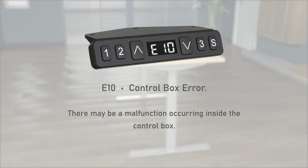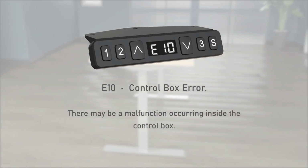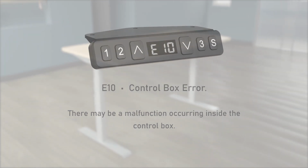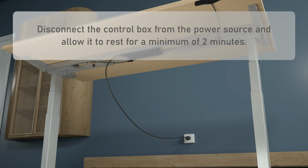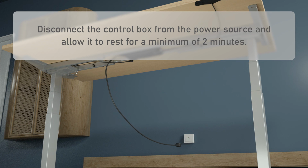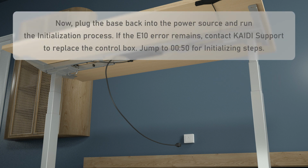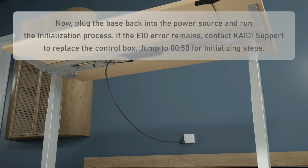E10, control box error. There may be a malfunction occurring inside the control box. Disconnect the control box from the power source and allow it to rest for a minimum of 2 minutes. Now, plug the base back into the power source and run the initialization process.